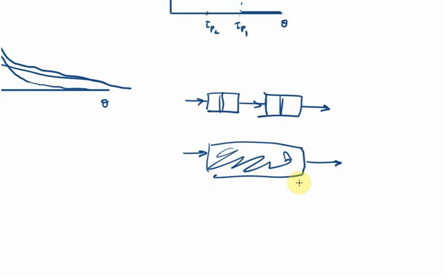Okay, I'm assuming you are unpausing and you've tried this now. So for a PFR, actually this is going to function as just one long PFR. So your tau, if we just label it tau P1 and tau P2, what's really observable is the sum of these two. So in effect, you just get the same RTD as for a single PFR.